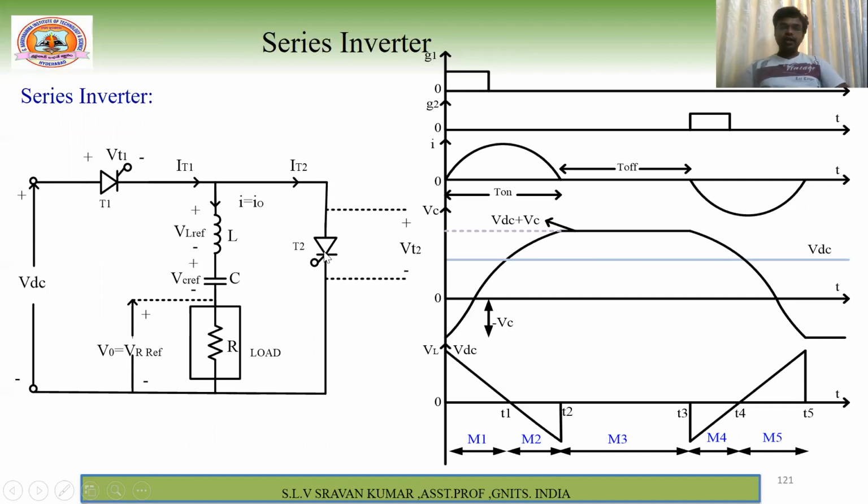So before studying this concept, if you go to the class A computation, it is easier to understand. Here, this is your I naught curve, the voltage across the capacitor, and the voltage across the inductor. Now see here, this is the R load. For this R load, the current flows like this, and based upon your current shape, your voltage will be developed. Since the output current shape is already sinusoidal, your output voltage shape is also going to be sinusoidal. Understand what I am saying?